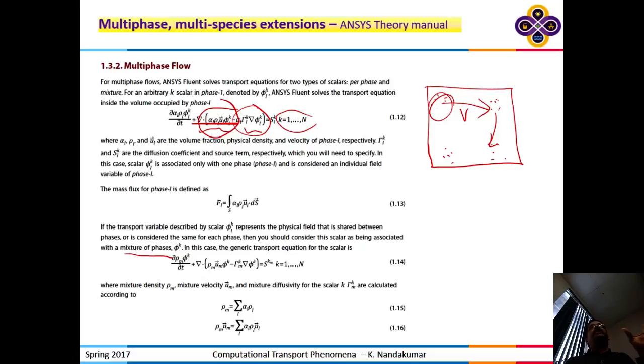Typically, if there is no significant density difference, for example, between the particle and the fluid, then the gravity is not pulling on the particles with different force than on the fluid, so the particle and fluid move with the same velocity. Then you can have one velocity field that is shared by both phases. Then a simplified version of this model, the so-called mixture model, is available in Fluent and in all the similar software. But you then define what is a mixture